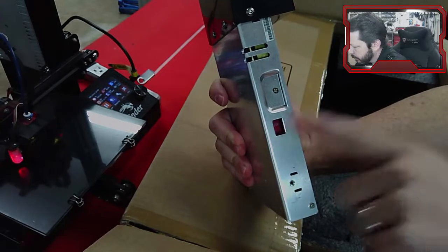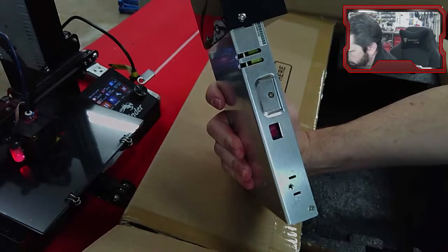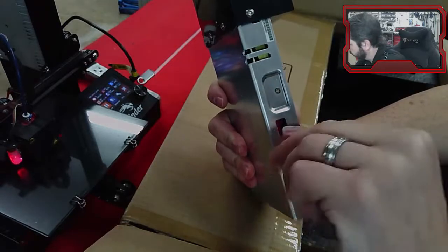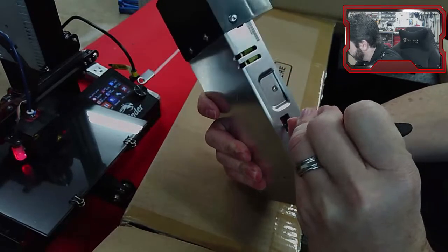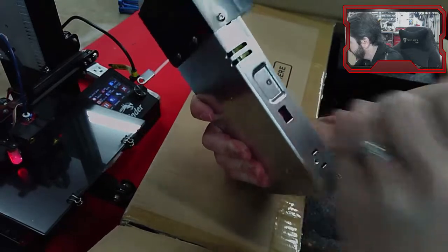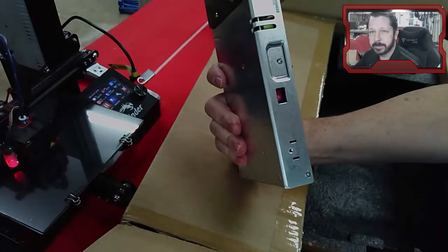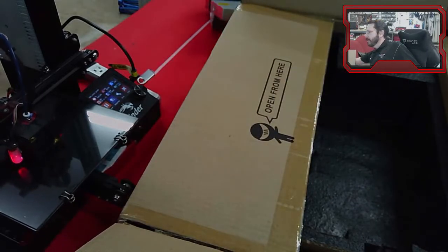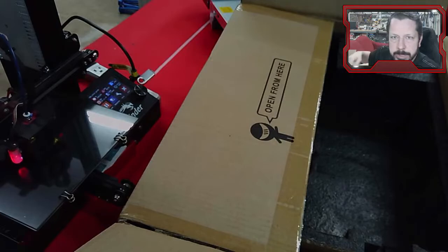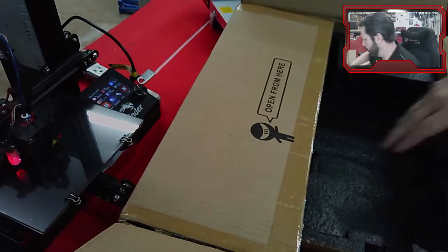So you have to slide this switch over to the 110 side, or it's not going to work right. So I might have to find a screwdriver to do this. No, there we go. So 115, now it'll actually do what we want it to do. It wouldn't hurt it if it was set to 230 and you plugged it into 115, but it wouldn't work either.